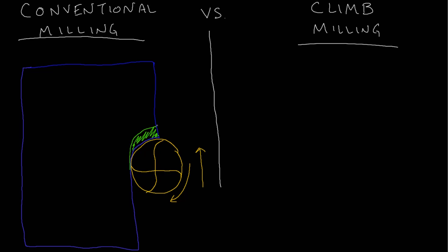And at the end here, this is what we call our feed per tooth. So if you order a tool, a cutter, it'll come with its own parameters of how much you can take off per tooth. For end mills, it's in the range of maybe 5/1000ths of an inch per tooth. All right.